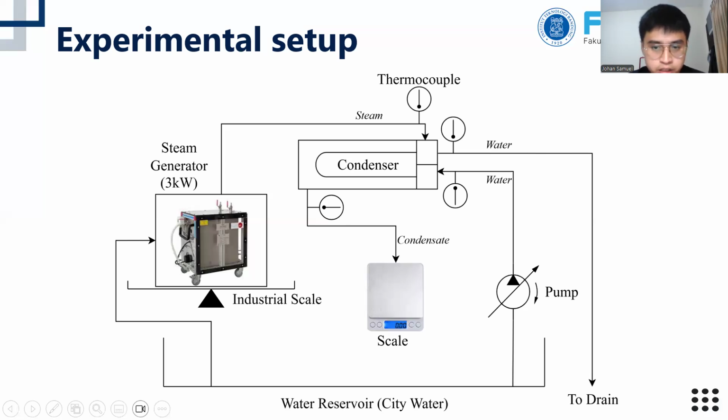And since it operates no longer than an hour, data is recorded every 5 minutes for 55 minutes. Furthermore, it is proved to be in a steady state since the mass for it is constant. The condensate from the condenser is discharged to the outlet port with thermocouples installed to measure the temperature. Then, the condensate is collected with a container and its weight is measured.